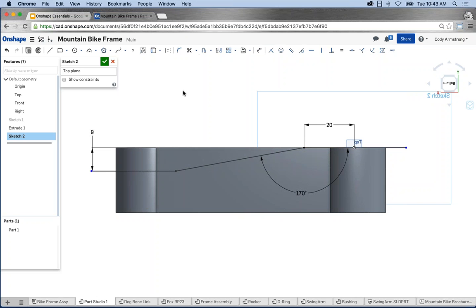And the easy way to do this is with the offset command. Now a tip is if you select offset and just left click a line, you're going to get an offset of just that one line. However, if you select offset, left click and drag, you will get an offset of all the entities, right? In this particular sketch, the 3 different lines. So I can drag out an offset of all 3 lines, left click, and we'll enter 8 as the amount for the offset. And the last thing I have to do here is just close off these contours.